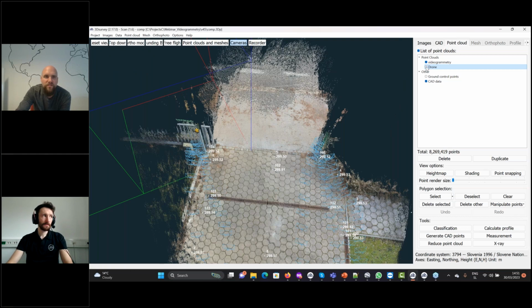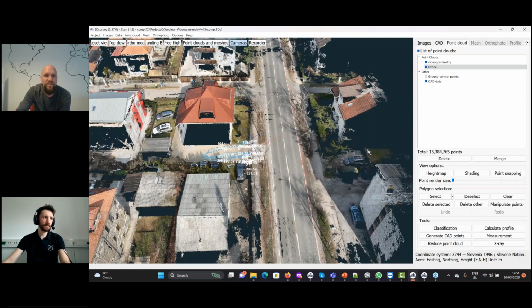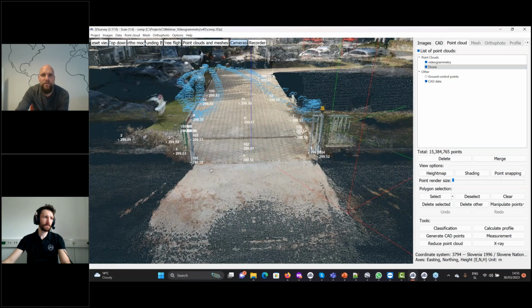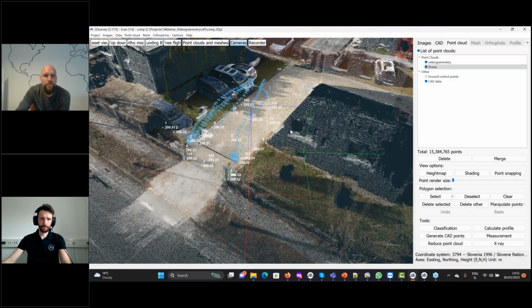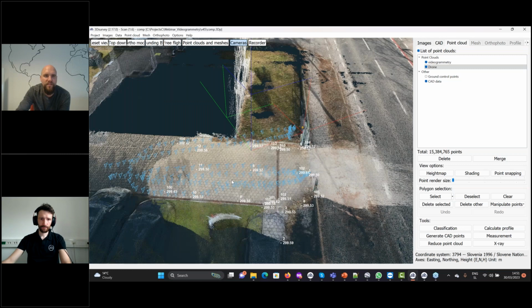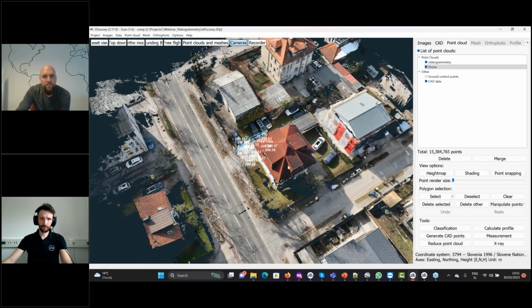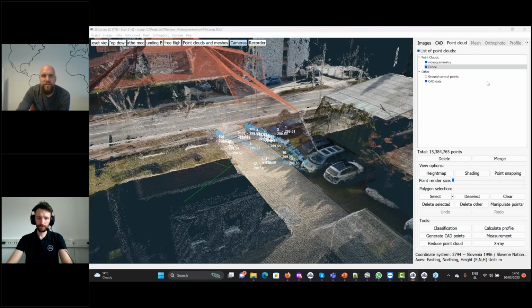But what was also interesting for this one, I combined this videogrammetry with my drone survey. So if we combine these two together, we get a pretty nice result. With drone photogrammetry, we get slightly lower density, and here where we focus with videogrammetry, the data is a lot denser. So this data can be joined and merged together.